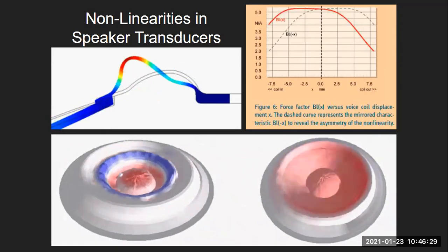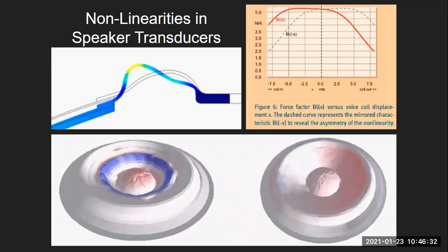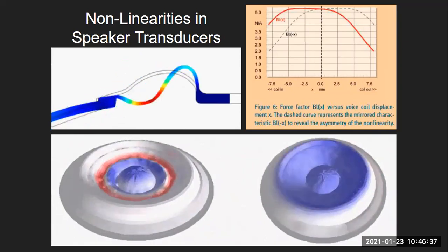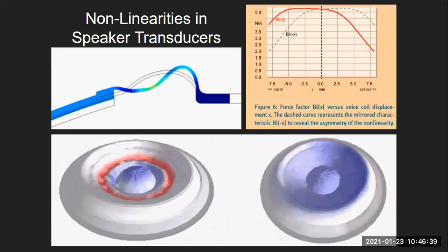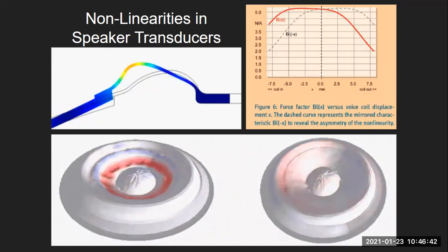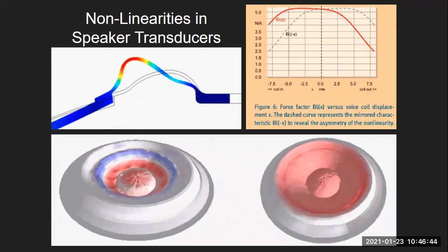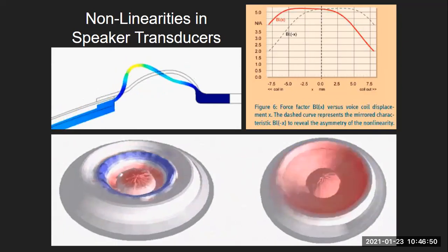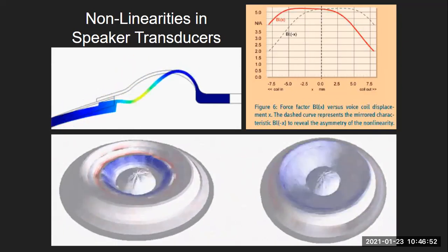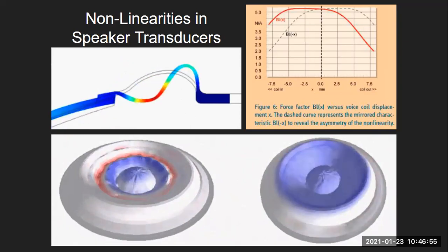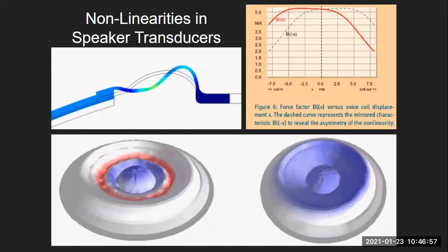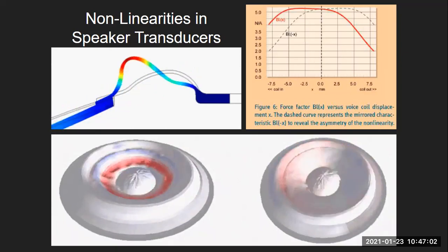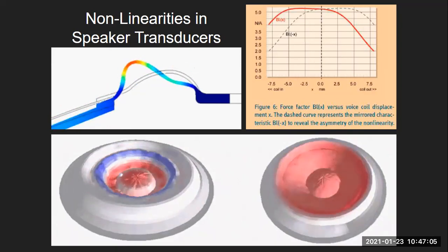On the left, we can kind of see what happens when the acceleration exceeds the limit of the material itself, the stiffness of the material. So you get this sort of ripple effect almost, and this is just one kind of breakup mode. That's what this effect is called, the cone breaking up. This would be a radial breakup mode, I believe. But you can also have... anyway, I'm forgetting all of my terms here.